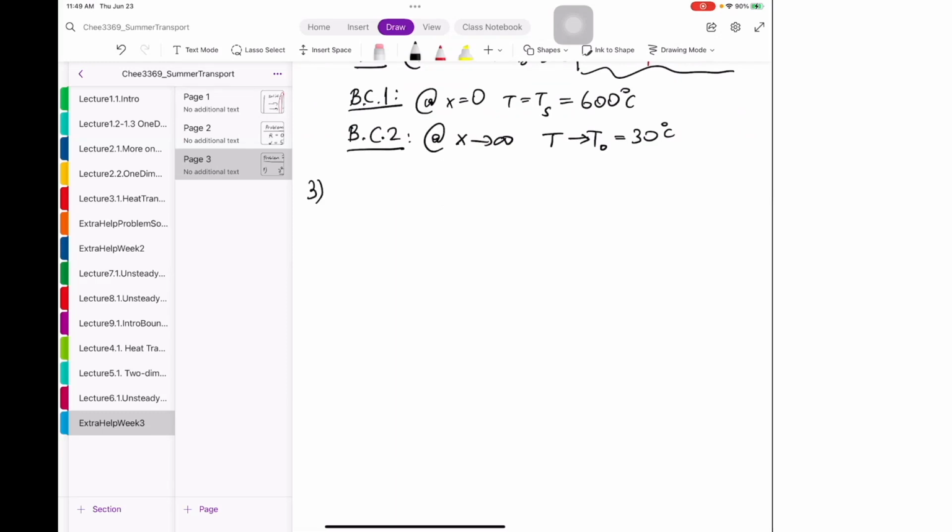Part 3, what are we going to find? We're going to find out the penetration depth after a given amount of time. It says particularly the material will disintegrate up to a depth where the temperature reaches 400 centigrade. Determine the thickness of the material which may disintegrate, meaning what is the penetration thickness if I just take the 400 degrees centigrade, if I want to observe the evolution of 400 degrees centigrade.